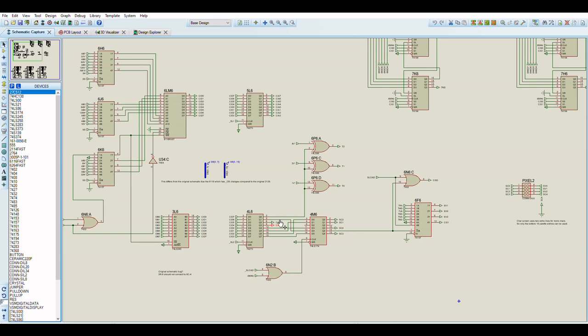So you've got up to 1,024 characters with the palette lookup plus horizontal and vertical flips, which means that the character screen, because it has 1,024 characters, doesn't use the full range of palette index lookups like the sprites and like the tiles can. So the character screen uses only up to a maximum of 128 colours instead of 256. That's kind of like an inbuilt limitation, because of these extra 2 lines here.